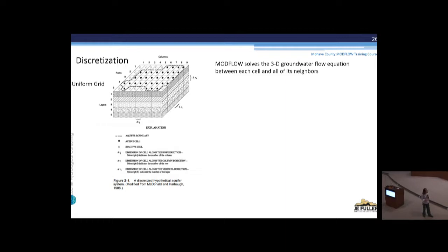So continuous layers, each cell here has a single homogeneous characteristic. So there's no distinction between properties across one cell, it's all one. And likewise, anytime you do something to a cell in MODFLOW, it applies to the whole cell. You don't just get to inject a well halfway down. In most cases, you have to inject across the entire thickness of that cell if you do an injection well. Or if you pump, your well may be screened only in the lower 100 feet, but in practice, it's basically applied to the entire thickness of the cell.